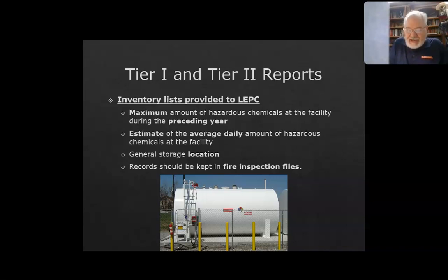These reports will contain a list of all chemicals and hazardous substances required according to the TPQ or the RQ, the common chemical name, the Chemical Abstract Service number, CAS number, the physical state, solid, liquid, or gas, the physical or health hazards, the immediate acute effects or delayed chronic effects, the inventory information, the maximum daily amount, the average daily amount, and the number of days on site. The storage information includes the container type, the pressure, the temperature, the specific information on storage amounts, and locations.